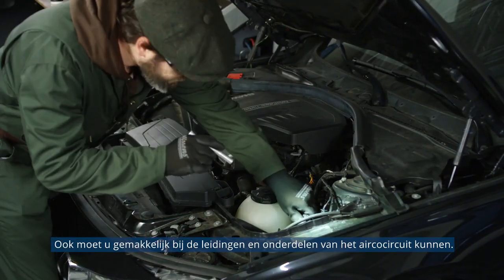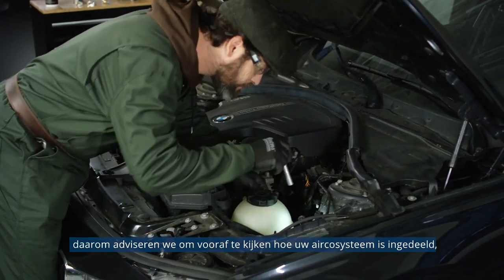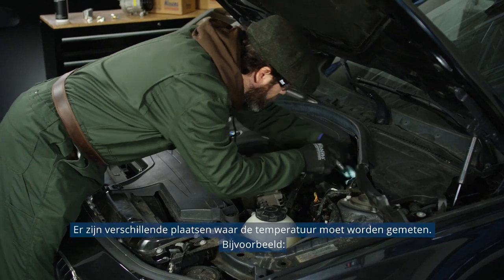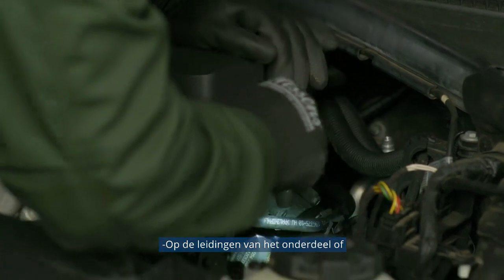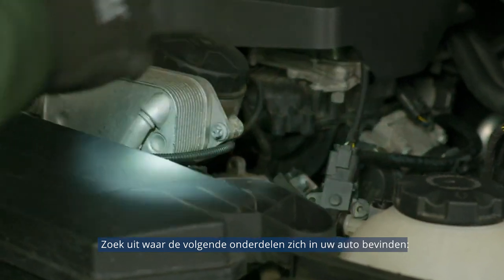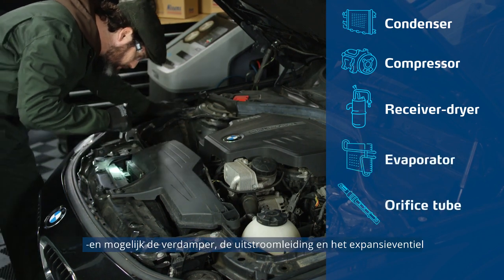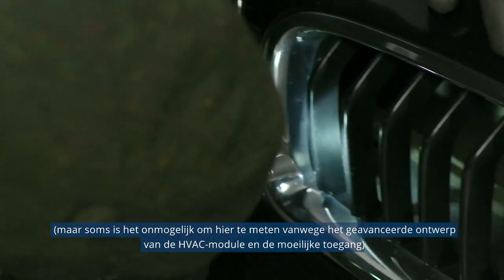You also need easy access to the AC loop ducts and components. Some of these can be hard to access, so it's recommended to learn your AC system's layout beforehand to get familiar with the design and the placement of the most crucial components to measure. There are several places where temperature should be measured: on the specific component surfaces, on the component's lines, or at the component's in and outlets, without detaching, of course. Find out where in your car the following components are located: the condenser, the compressor, receiver dryer, and possibly evaporator, orifice tube, and expansion valve. But sometimes it can be impossible to take a measure of these due to the sophisticated design of the HVAC